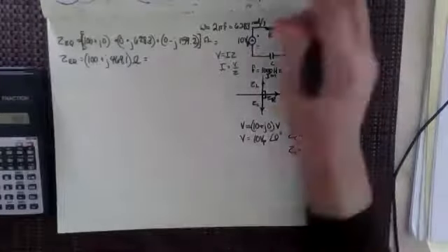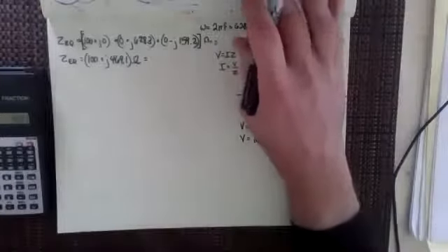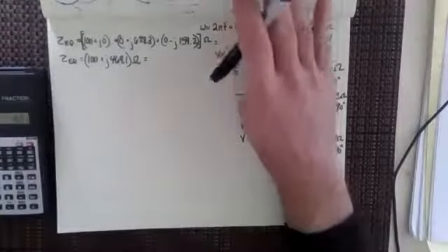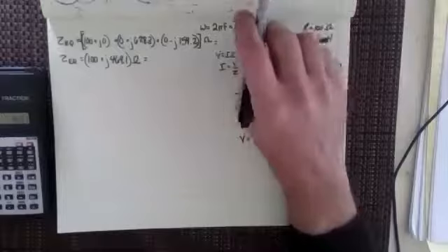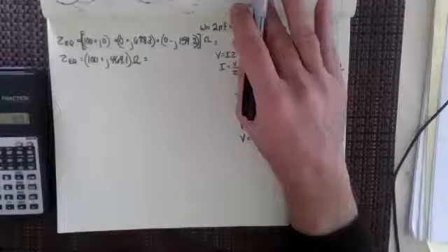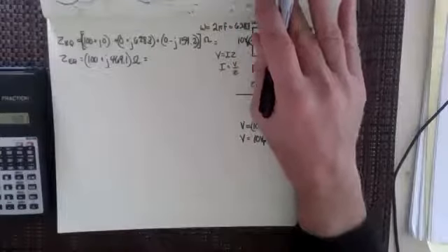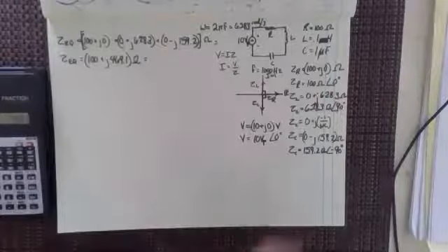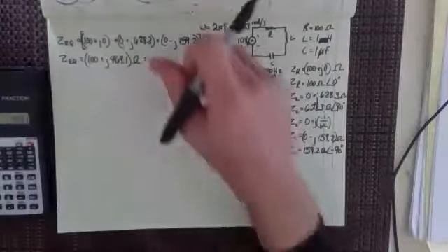So later on, we have to keep it in our mind that we're always talking about peak voltages and not RMS voltages, so that when we do the power equation later on, we're going to be using RMS voltages, not peak voltages. But up to that point, as long as we keep track of everything we're using, we should be fine.